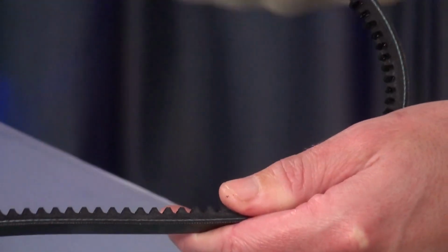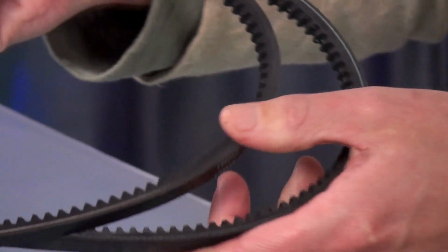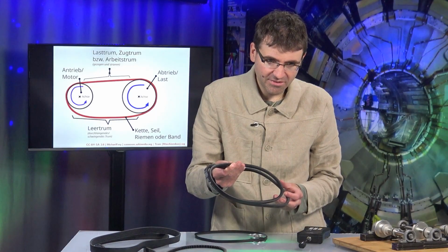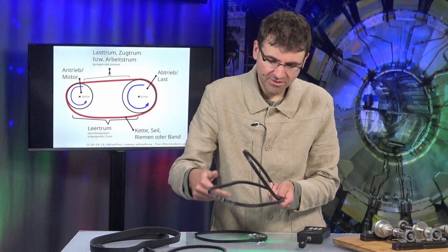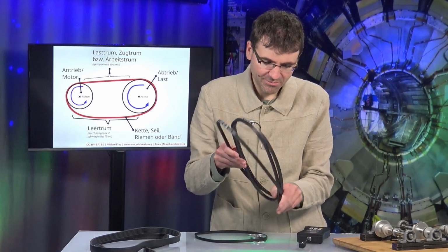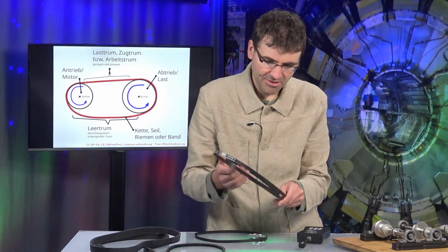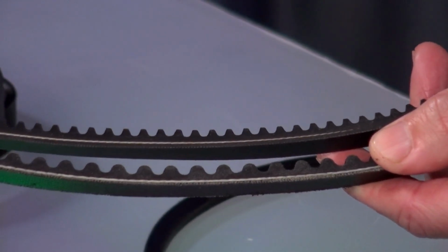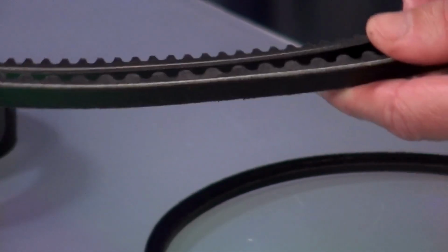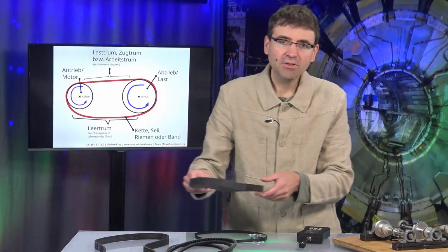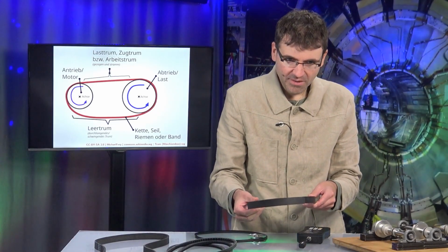And I can place a second belt over this one. We observe that it has a different length. However, the teeth themselves are identical in size, whereas another model possesses the length corresponding to the previously mentioned model. I set this down. However, here we observe that the teeth are larger. We have various selection possibilities here, depending on the required force and the necessary length. Other variations also exist, which we can observe right here.